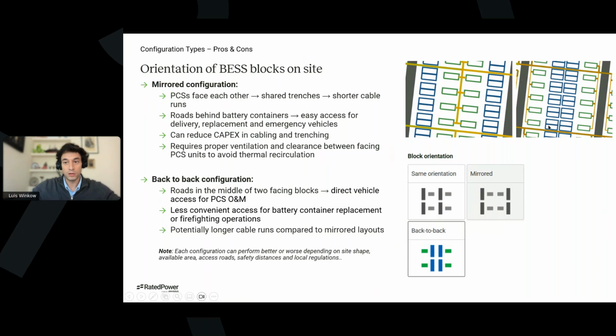So also having that in mind, maybe it's more useful to have the roads near the containers, as you need more heavy machinery, as for the PCS, where you can maybe walk and do your maintenance. There are also potentially longer cable runs compared to mirrored layouts, as you're not sharing as many trenches as in this other layout.